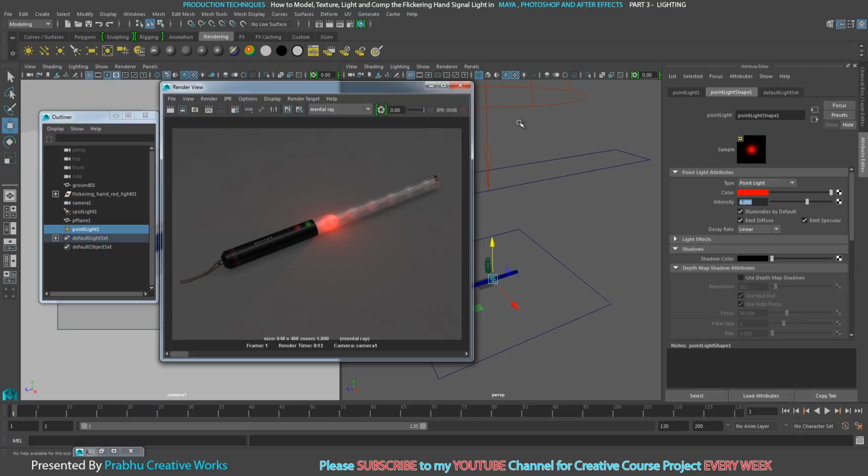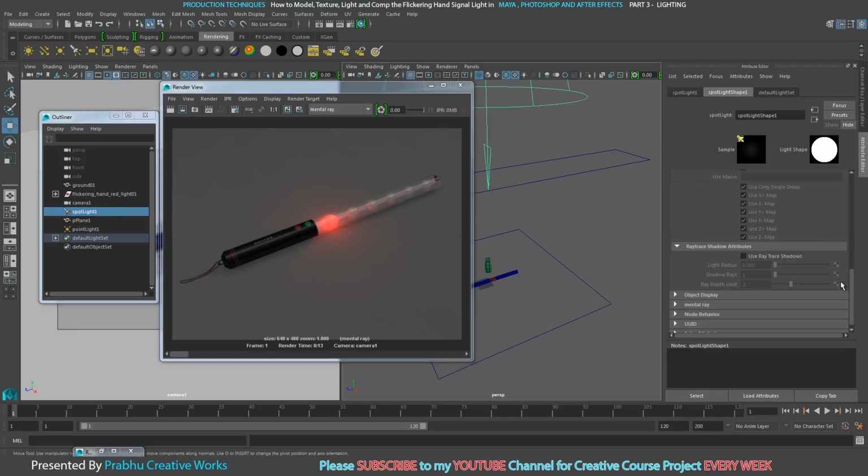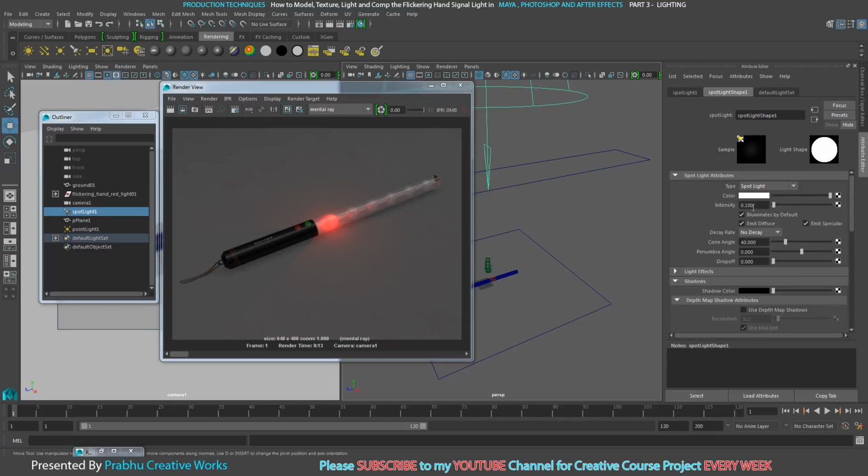So then I want to reduce scene intensity a little more. So I will select my spotlight and go over intensity. So it's 0.1. I will reduce to 0.05 and click. I will keep the image and click render again. So I got very little lighting in our scene.